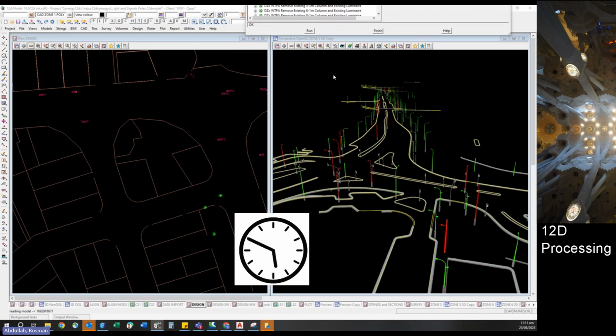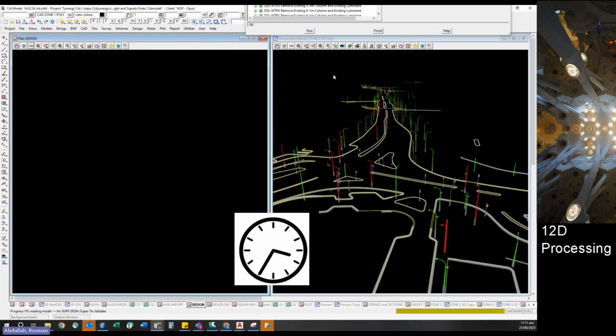Essentially, the first steps are that it cleans out all the relevant models, reads in the DWG that we have updated, and then it takes those CAD elements, drapes them to a supertin, and from there's the long list of BIM object applications mapped from the different visibility layers in CAD, and ideally that should be the entire process.